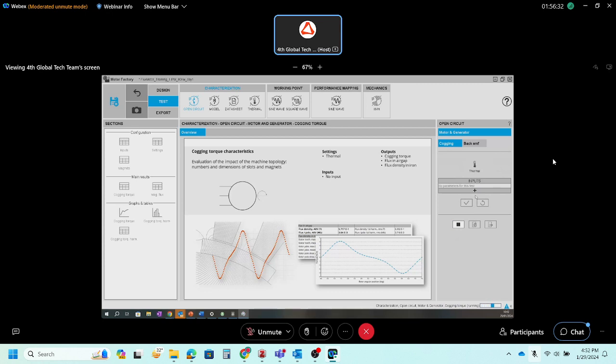About the air gap mesh coefficients, if you put 0.1, for example, you will have a higher density of the mesh in the air gap. If you use a bigger value like 1, for example, you will have fewer elements.